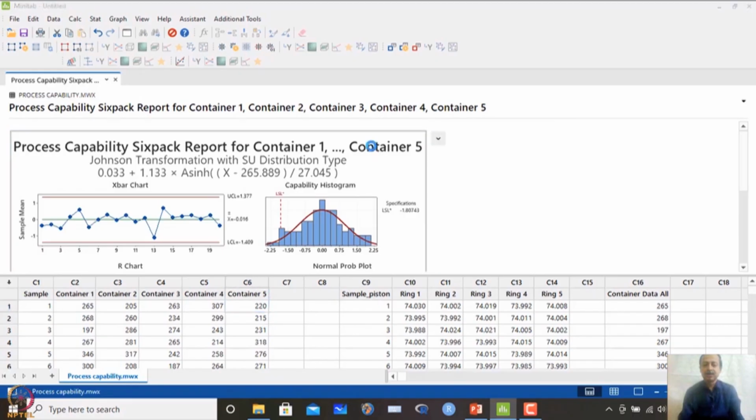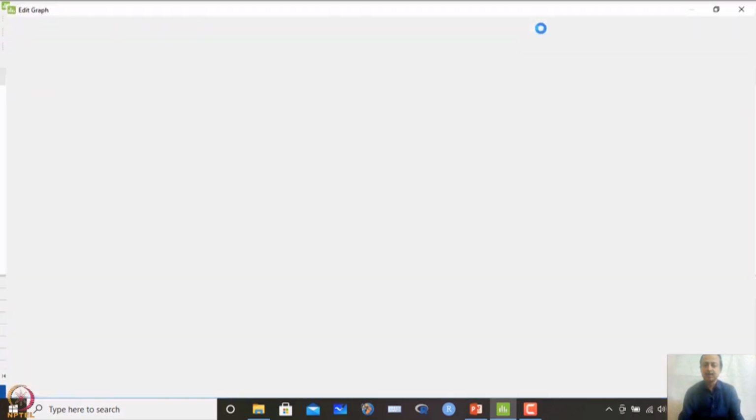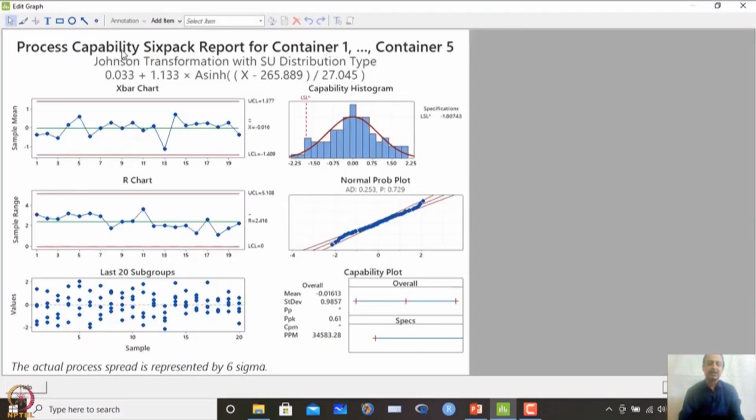Okay. So, when you click this diagram over here, what you see is that it has used a family of transformations. In this case, the transformation is done on the y characteristic, you can see x. So, x will be replaced, let us say, by y. You can think about the data that is given as y information, or CTQs, generally we express like effect, that is the CTQ. So, the final outcome is the CTQ and that is y. MINITAB says that we have transformed with a symbol x like that, the data set is x over here.